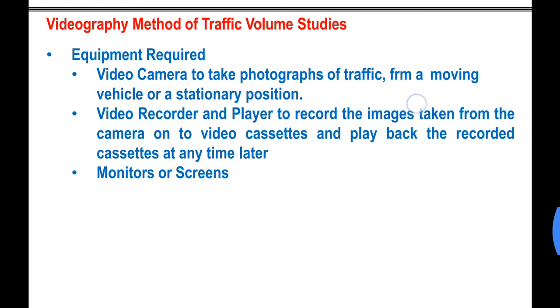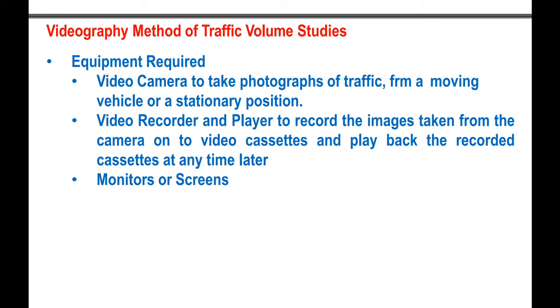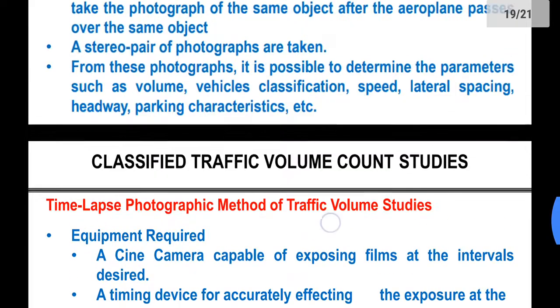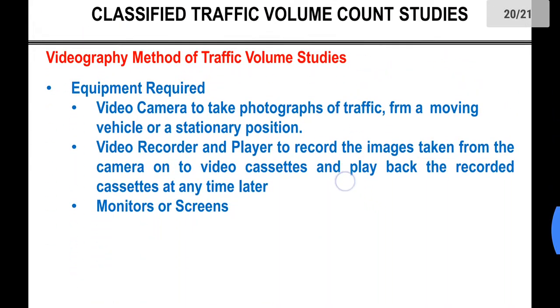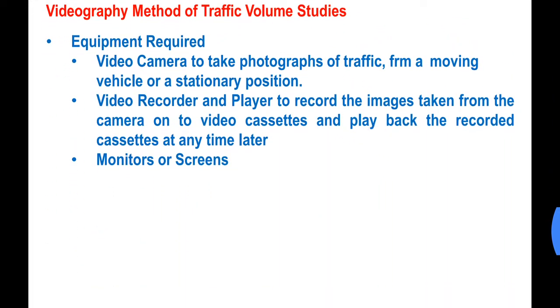Now the next type is the videographic method. In these methods, what we were doing is taking photographs, but in the videographic method we just record the video, and using that video we count the number of vehicles for different time intervals.